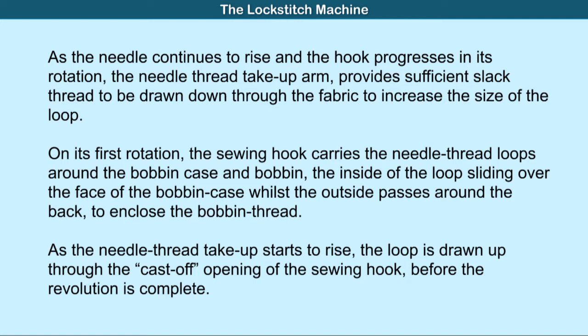As the needle continues to rise and the hook progresses in its rotation, the needle thread take-up arm provides sufficient slack thread to be drawn down through the fabric to increase the size of the loop.